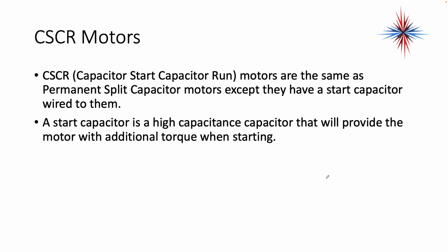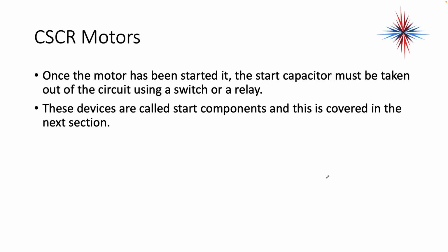Okay, a start capacitor is a high capacitance capacitor that will provide the motor with additional torque, or an additional kick, when starting. Once the motor is started, the start capacitor must be taken out of the circuit using a switch or a relay. These devices are called start components, and this is covered in the next section.